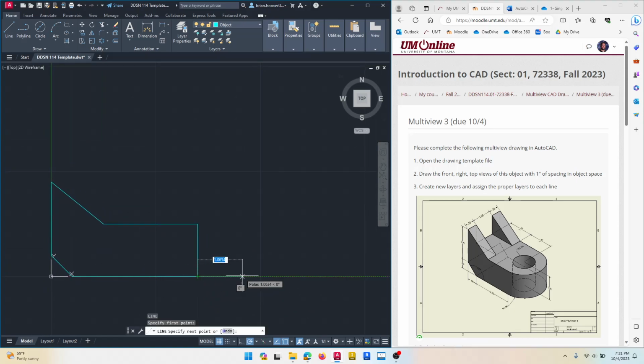So now I can go over 1 inch, start my right side view. So the height is 2.25, coming in 0.5 on both directions. Then if I do the math, this is 1.25, this height right here. So this is 1 inch. 0.5, 1, this width is 1, 1, 0.5, 0.25, and then I can double check. So my width is 2, so just remember 2, or right here I've got a radius of 1 for a total of 2.